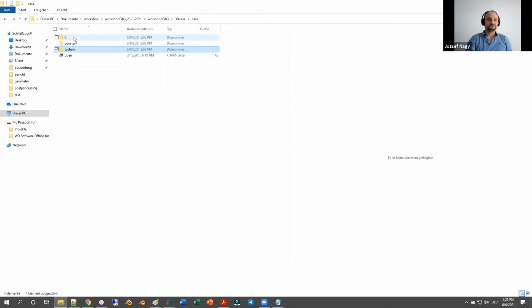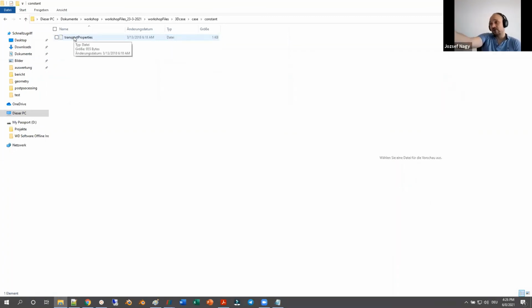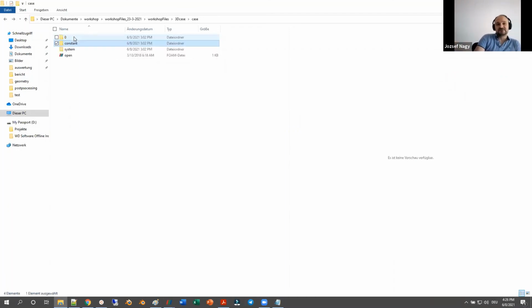In 0, depending on the physics that you want to solve, you have 2 or more files. You have to watch out which ones you need for individual solvers. But you can learn about this on my YouTube channel or in other trainings in the workshop. Then here you can define your viscosity, and then in controlDict you can change your end time. Then in the 2D cases, we imported the mesh from Fluent format, and we just ran the simulation to have first simulation results.